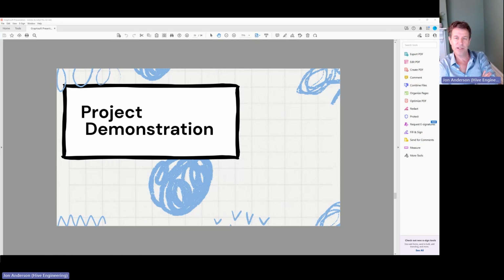I have to be careful with the libraries that I've got because I can't bring a library that's saved in Archicad 26 back into Archicad 24. So if I've got an architect that's still using an earlier version of Archicad, it makes it really difficult if I bring my library forward. So I try and keep my library back a few versions.